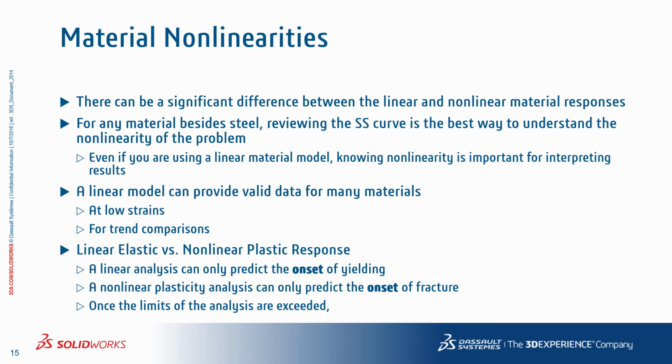So one final note on this, and this goes towards correlation and prediction of analysis results to test data. A linear analysis can only predict the onset of yielding. Once a reasonable portion of the linear model begins to yield, the loads all redistribute and it becomes a different problem. Attempting to correlate the final prototype that is loaded to failure to that of a linear analysis will not make any sense.